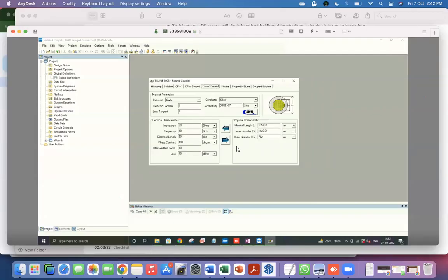And we focused on two things. The characteristic impedance, of course, is the main thing we are mostly interested in. But the other thing is the electrical length, and especially the connection between the physical length and the electrical length. Because as we have seen, lambda by 4 and lambda by 2 have special properties, and we're going to be using those sections later on to build different kinds of circuits. So it's important to know, when you're actually making these devices, what is the actual length you need. And this kind of tool helps you to get started.